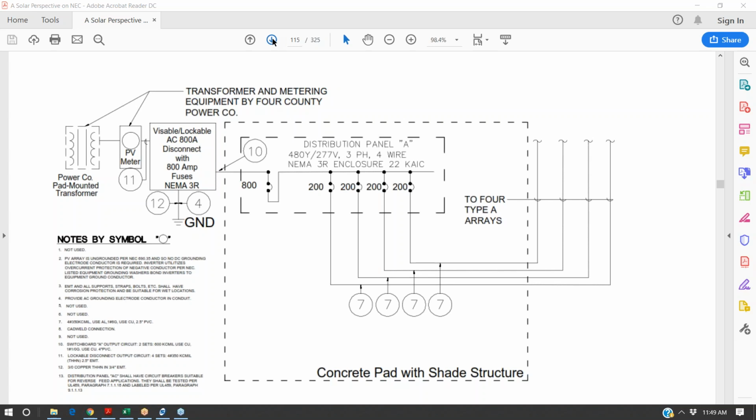Then again, that resettability of the breaker isn't the best thing in the world, because breakers shouldn't trip for no reason. It's quite rare to come across a bad breaker as opposed to a ground fault due to poor workmanship. And so having a resettable breaker where the breaker trips and the client just goes and resets it, there's usually issues that need to be looked into and diagnosed and addressed, like loose connections.